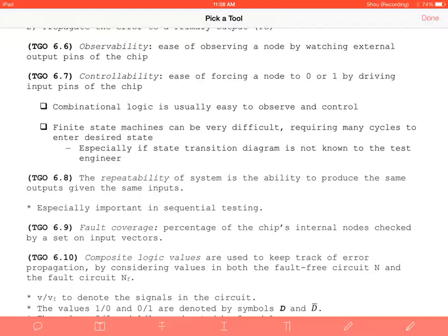How is it affected when you're trying to propagate a token to the output? How is it affected when you actually have your switching occurring? So if it repeats but then stops repeating, there's some sort of input combination or some sort of hold or delay time that could possibly be affecting your error.